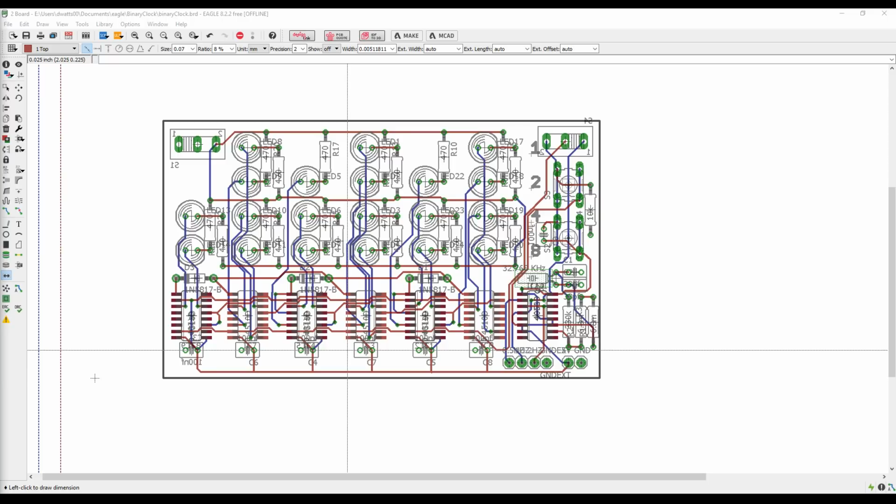And Howard says they're a nightmare to solder unless you have a reflow oven. Yeah, the smaller parts can be. I think 1206 is probably okay for most people, but anything smaller than that, and you're in danger of people with poorer eyesight having trouble putting the parts in the right places and reading the tiny marks in the solder mask. So I'd rather make it pretty accessible. Plus, if kids want to do it, I'd rather it be through hole. I mean, if it was all through hole, it'd be a great way of learning electronics.